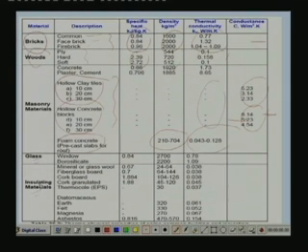These kinds of properties are available in air conditioning design data books such as ASHRAE data books or other air conditioning books. Looking at the tables, you can take the properties like specific heat, density, thermal conductivity or conductance. If you are calculating the overall heat transfer coefficient, you can use either the conductance value or the thermal conductivity and thickness, and find the overall heat transfer coefficient. From the overall heat transfer coefficient and the temperature difference you can find the heat flux through the wall.